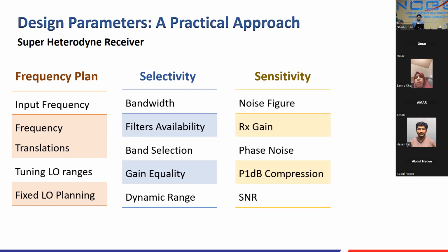Now, what is the effect of phase noise? When you input a signal into a spectrum analyzer from an oscilloscope or a function generator, you get a single peak. But when you reduce the span of the signal, it becomes a skirt. That skirt of the signal is actually due to the phase noise, the spread of the signal. Now imagine you are interested in a signal strength, you want to measure around minus 83 dBm, minus 90 dBm signal, and your skirt is that wide. So your LO will actually mask the weak signals in that skirt, and you won't be able to detect them. So phase noise, in any receiver you see commercially from any vendor, there will be a parameter of phase noise. How much phase noise there is is the measure of the fall of the skirt of the main LO or the receiver frequency. That actually contributes to the sensitivity of the receiver.